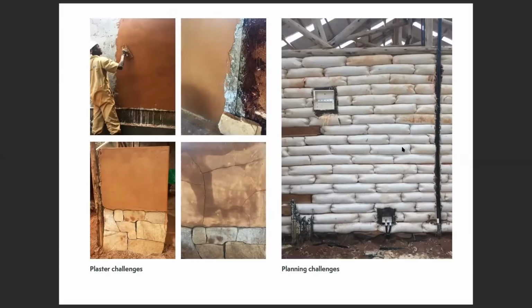We have shown this before in the beginning, where Edson talked about how doors, window frames, etc. are actually fixed to it. Well, you need to prepare for all these and essentially insert little timber supports into the wall at that very moment. Wherever you don't do that, you will struggle later to put them properly in place.